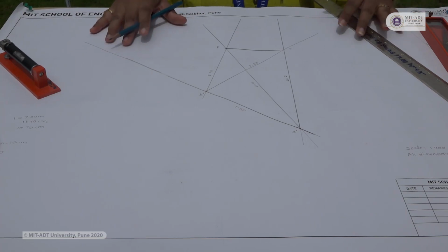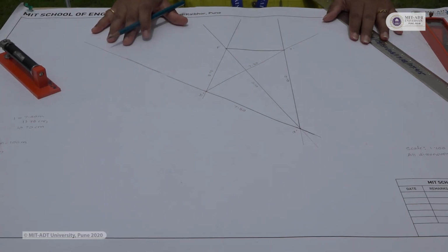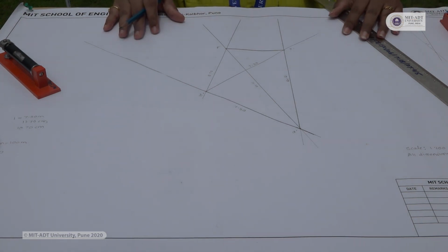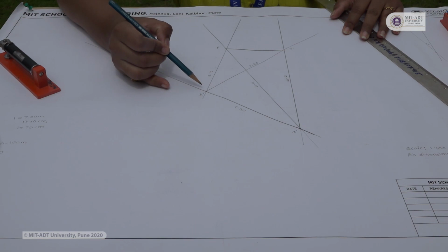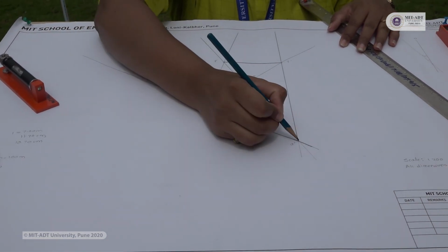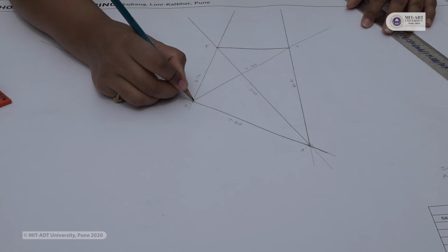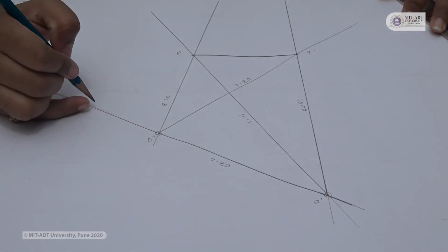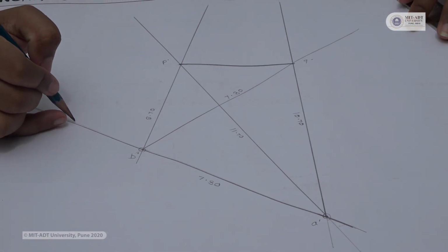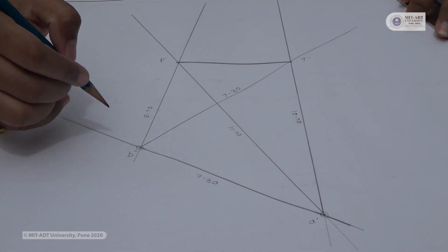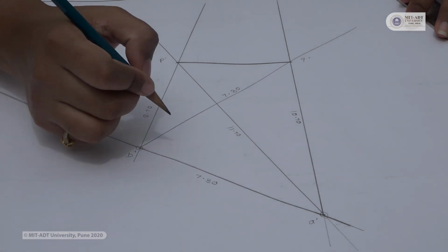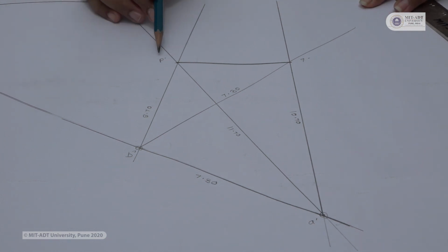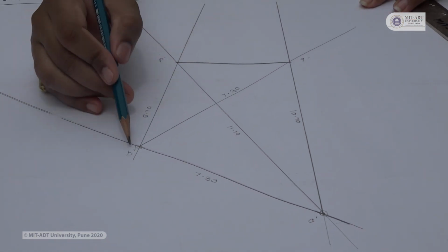So, we will just have a look at what we have drawn on the paper. So, on the paper you can see that I have marked the north direction, then I have written down the scale, and these are the different rays which I have drawn. So, these are our 2 stations, that is station A and station B. So, I will write down the name as A dash and B dash. Then after drawing the rays, by converting our dimension by using the scale which is 1:100, I have marked this point B dash. So, similarly you can see that different rays are drawn to our different objects. So, this one is P dash, this one is Q dash, this one is B dash.